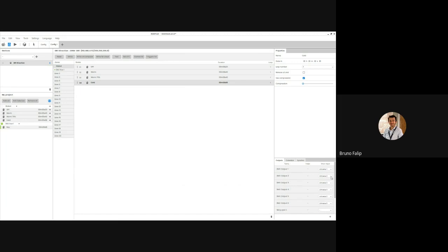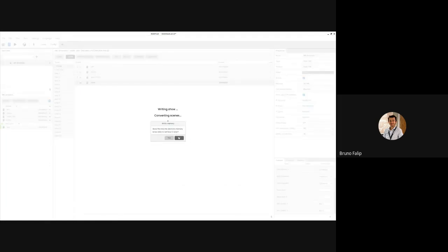From the output, standard is DALI output 1, output bus 1, DALI output 2, output bus 2. But you can reverse this like with DMX. You could send the same command to output. I mean, you do whatever you want. And when you want to write the memory, just press the write button here. Okay, and this is done.